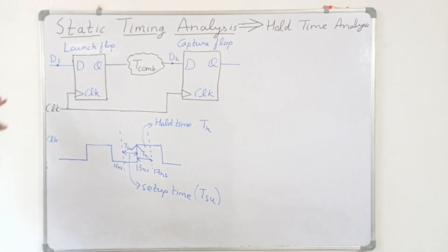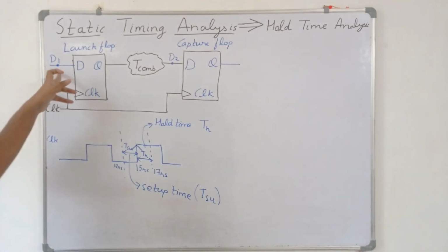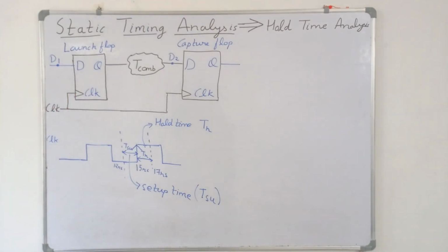Now, during the setup analysis, we have to ensure that the data which is launched by the launch clock at the current clock edge must be stable at the input of the capture flip flop at least setup time before the next clock edge.